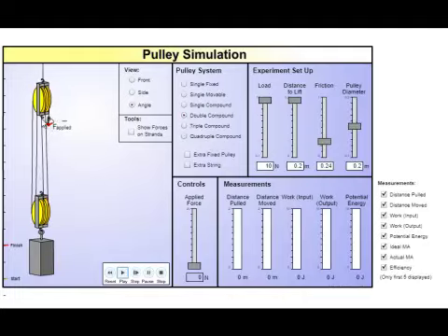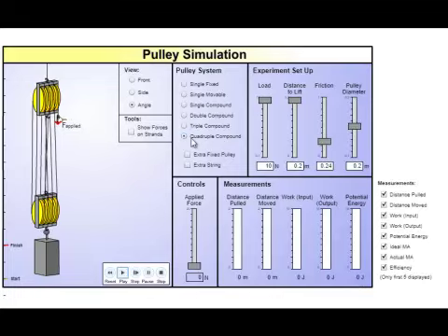By the way, notice that the first line segment is attached to the upper pulley, and that therefore we will get an even number. Sometimes I rig it up in the lab just like that, starting at the upper pulley, sometimes at the lower pulley, at which point I actually end up with an odd number of line segments. But that doesn't matter as far as figuring out the experiment is concerned and taking the measurement. In any case, we have 4, 6, and 8 segment lines or line segments, which you will find in the table in the lab menu.